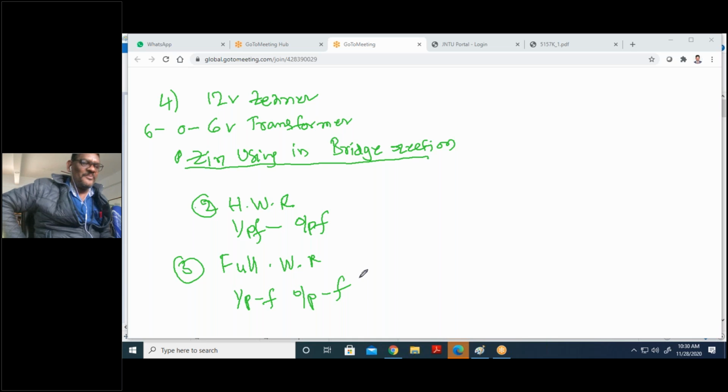Okay, now my job. What am I given first? Which Zener? What is written? Read first. 12 volts Zener diode. If the input voltage is more than 12 volts, your Zener diode in reverse bias conducts current.